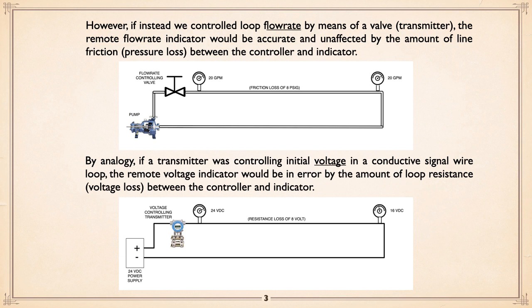Let's pretend we were dealing with power, electricity. We want to convey a signal. And let's say, as you can see, we've got a power supply at 24 volt DC, and we've got a transmitter, you can see with the blue circle on it and connections. We've got probably a pressure transmitter that is sending a signal value, and it's throttling that.